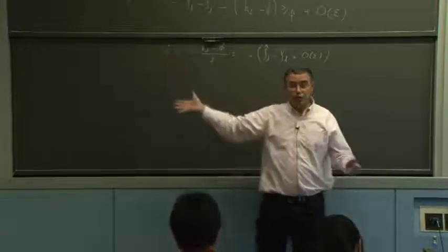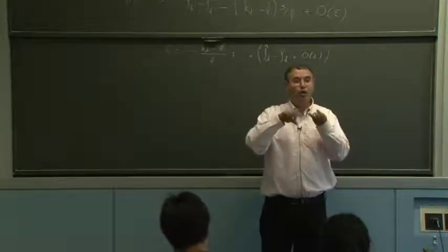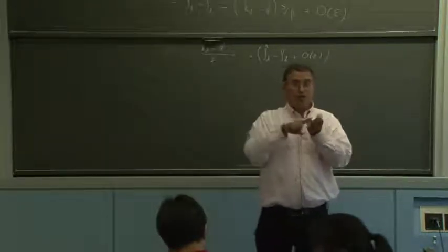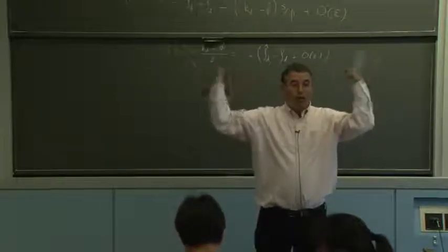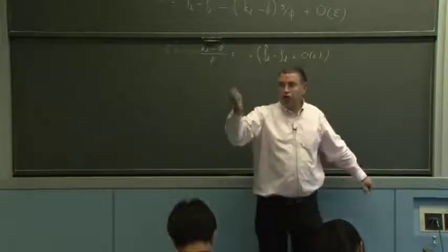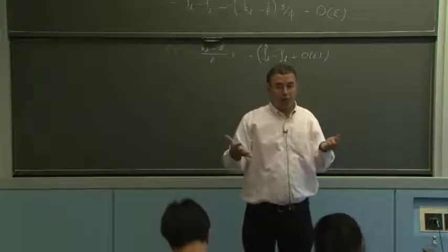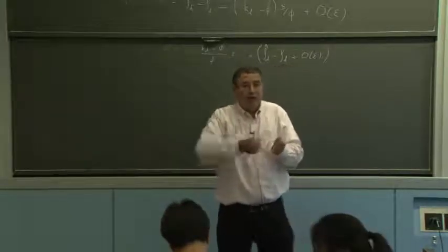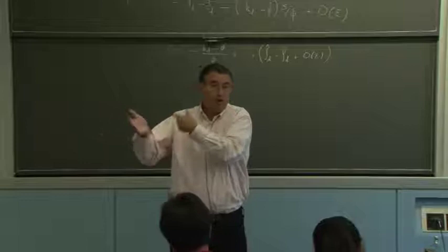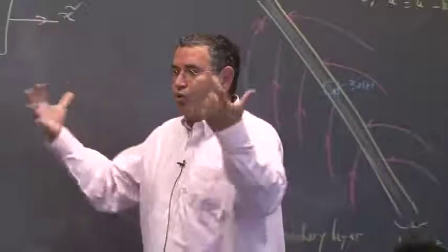So in other words, here where I say U equal, it means I have instantaneous measurements, instantaneous computation, instantaneous actuator, right? None of these assumptions is true, of course. That's what's called high frequency unmodeled dynamics, or fast unmodeled dynamics. And so what we're trying to do is be consistent, so that nothing here gets any faster or gets near, within a factor 3 or so, of these fast unmodeled dynamics. Because then we don't really know what's going on. So it's just the idea. That's why I'm saying it's on the back of the envelope, right?